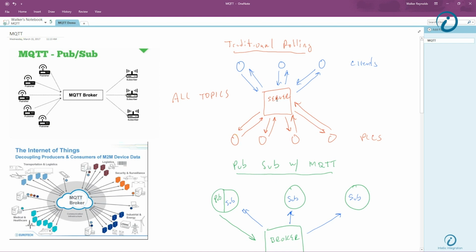You have your OPC server here in the center. I do some configuration in my server. I establish a connection with my PLC. I tell it how often I want it to get my tag updates. Do I want to respect the client scan rate? Do I want to scan at my own rate based on the server? And then I call out, hey, PLC, send me all your tags. And the PLC says, oh, here you go, here are all my tags. And then I go to the next PLC: send me all your tags. Send me all your tags.